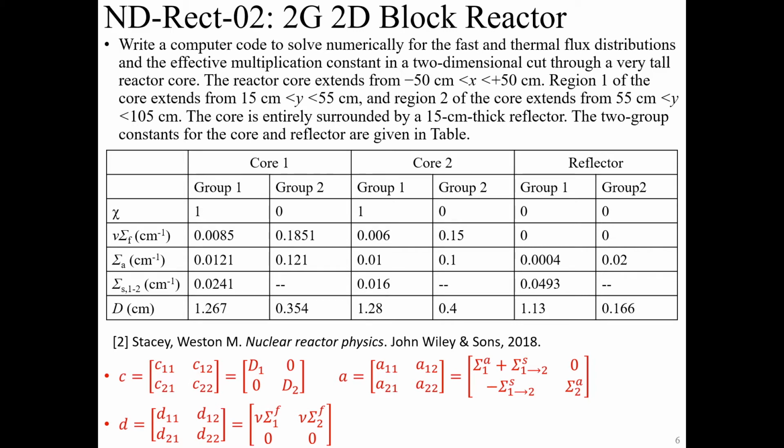Fortunately, we have MATLAB, so we don't have to worry about how this equation is solved internally. We just need to learn how to describe this model using the MATLAB PDE Toolbox. This is a very tall reactor core, so the z direction is infinite and it is a two-dimensional problem. The reactor core extends from -50 to 50 centimeters for the x.